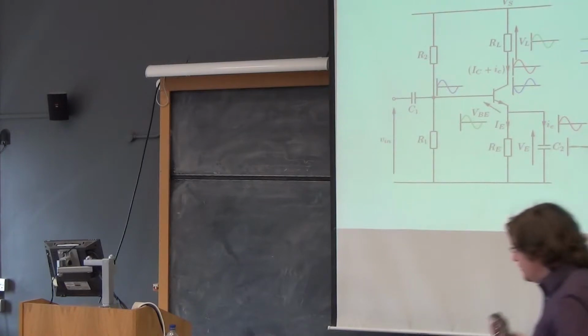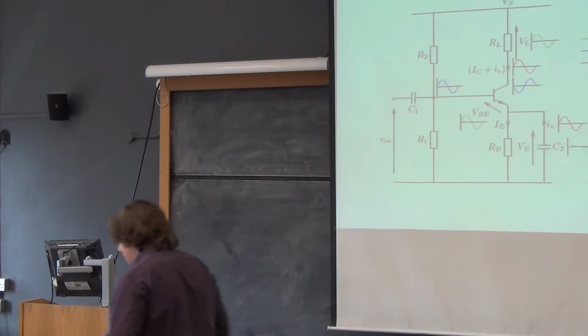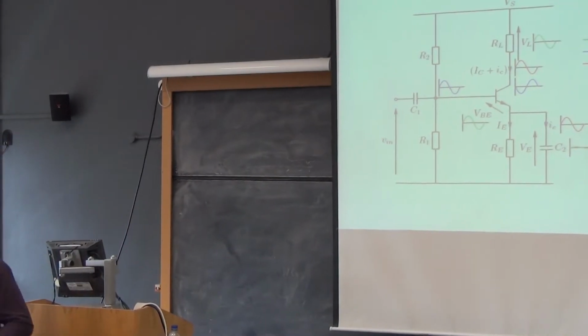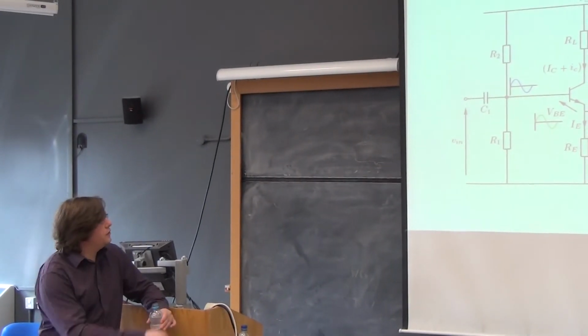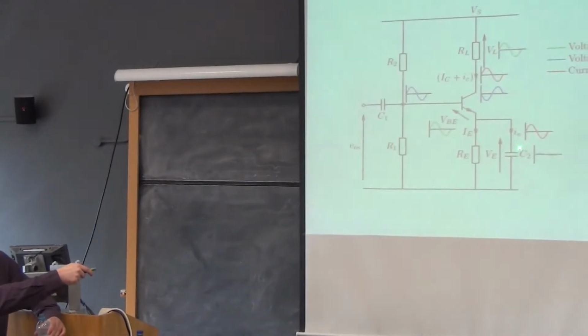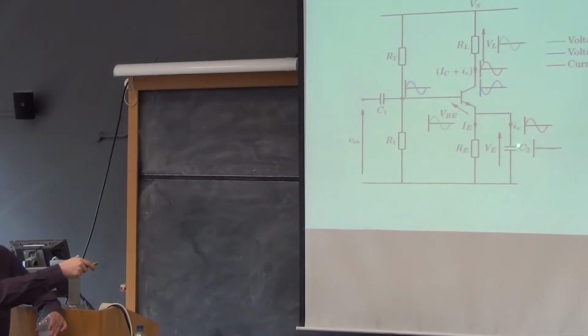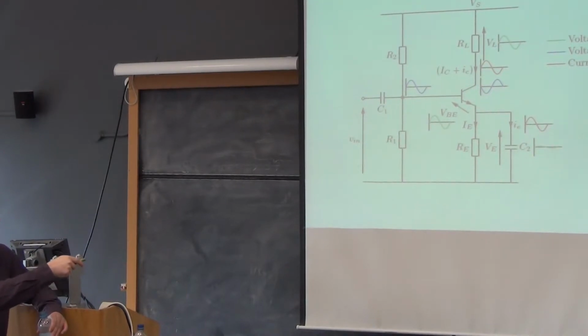So, just in case you didn't hear it, the capacitor is an open circuit as far as the DC is concerned. So, from DC's point of view, this capacitor does not form a pathway that it can flow through. So it must take RE. The signal, on the other hand, sees a reactance, which is what equation? Or impedance, if you prefer. XC is 1 over 2 pi FC.